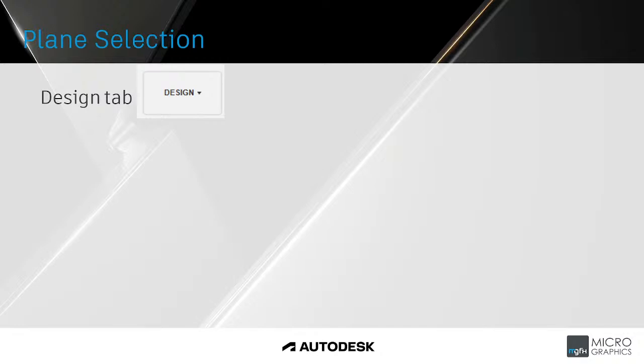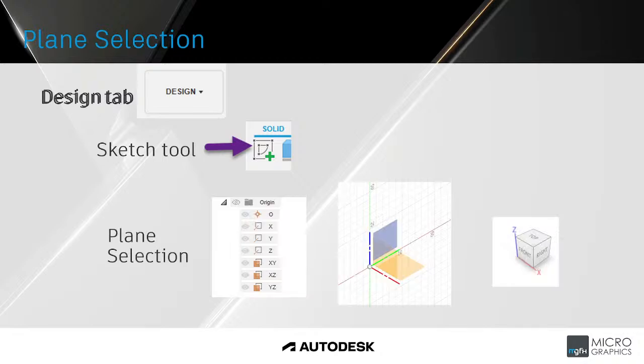To start a new 2D drawing, make sure you have selected the Design tab. Select the Create Sketch tool. After you've selected the Create Sketch tool, you'll notice on the screen that the different planes will appear in the browser. On the left side, under the origin, you will be able to see the different planes in accordance with the planes in model space.